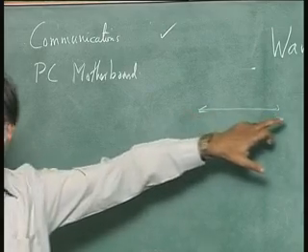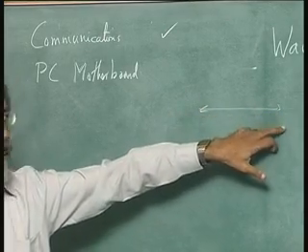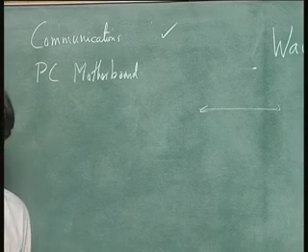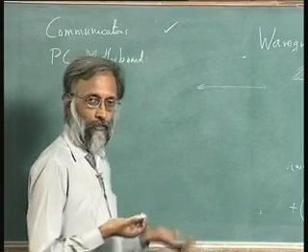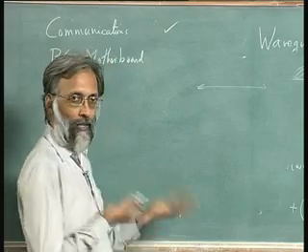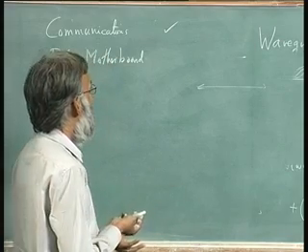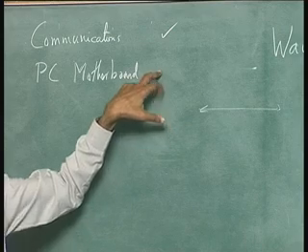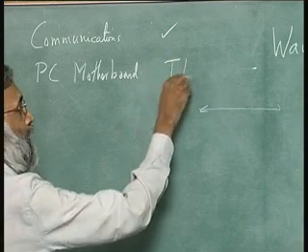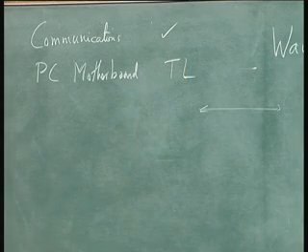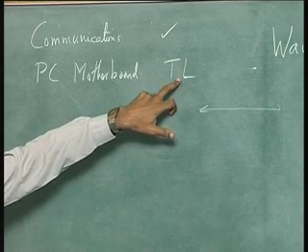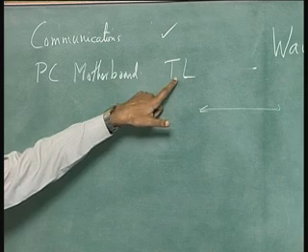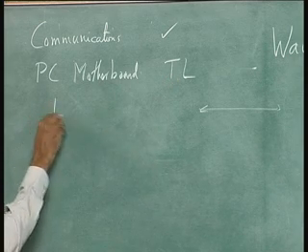the lines on a PC motherboard is a few centimeters, and the speed of the clock on the motherboard is hundreds of megahertz, combined together so that signal delays become very crucial. So once again you find transmission lines are crucial. If you don't take proper care about delays, you don't properly understand your transmission lines, you can't design a good motherboard.